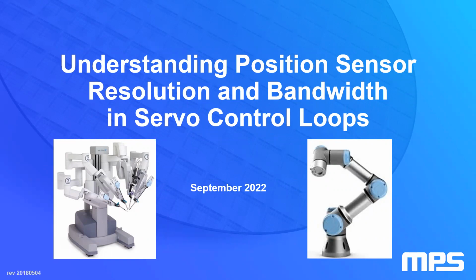Today we're going to talk about resolution and bandwidth in servo control loops. And it's a classic trade-off. It's a classic switch that you can play with, especially in magnetic sensors, where you can adjust an external filter and trade off lower bandwidth for higher resolution, or lower resolution for higher dynamic bandwidth.